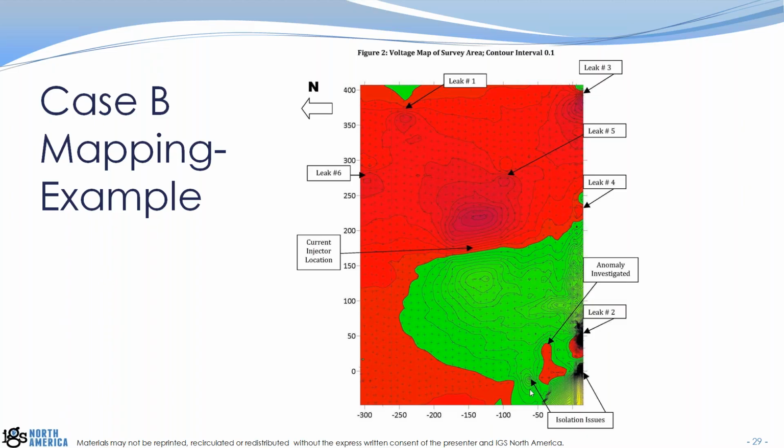This site had some isolation issues. So each one of these locations, you basically just go and inspect and make sure that the current draw is originating from outside or some current breach. This is the big leak in this survey area right there. Whenever you see the black, that means very close contour lines, so very, very large peaks. But you can still see something like this little leak in here. So again, you're looking for the bubbles, negative below the positive, and this one as well.